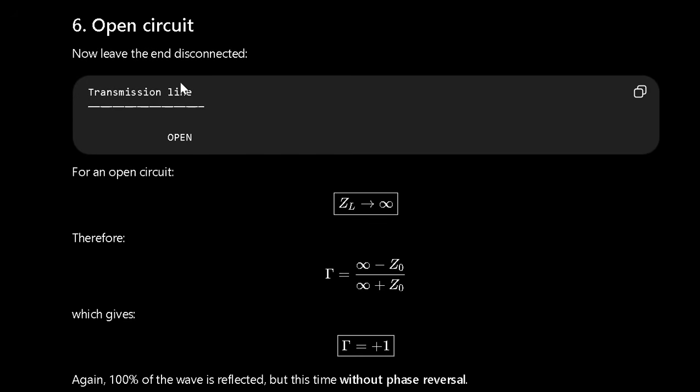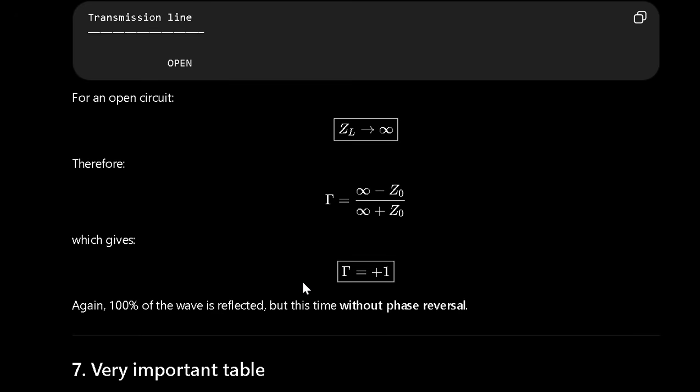For an open circuit, the transmission line is open, which means there is an infinite resistance, air. So air is infinite resistance, so ZL is infinite, so (infinite − Z0) / (infinite + Z0). Here he used just one method to calculate. What he did is take ZL minus Z0 over ZL plus Z0, and divide by ZL.